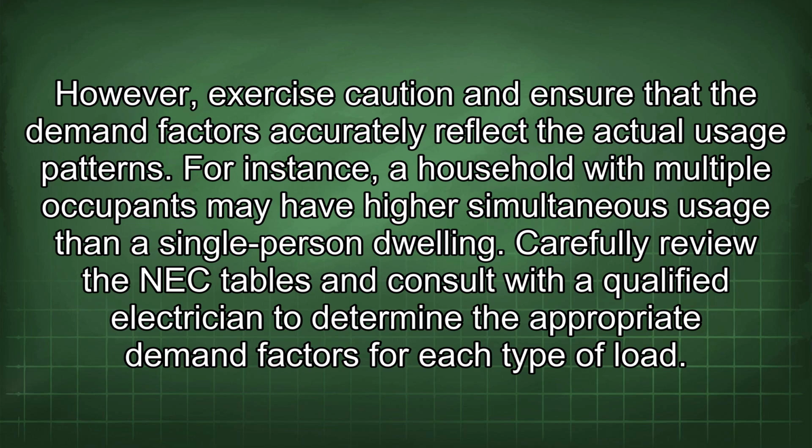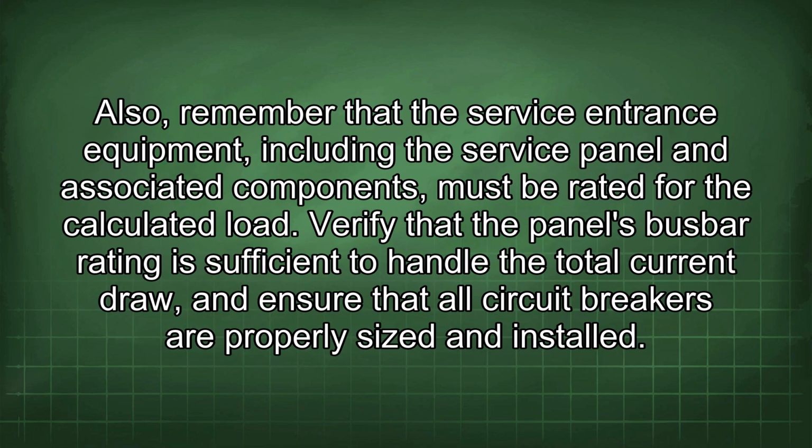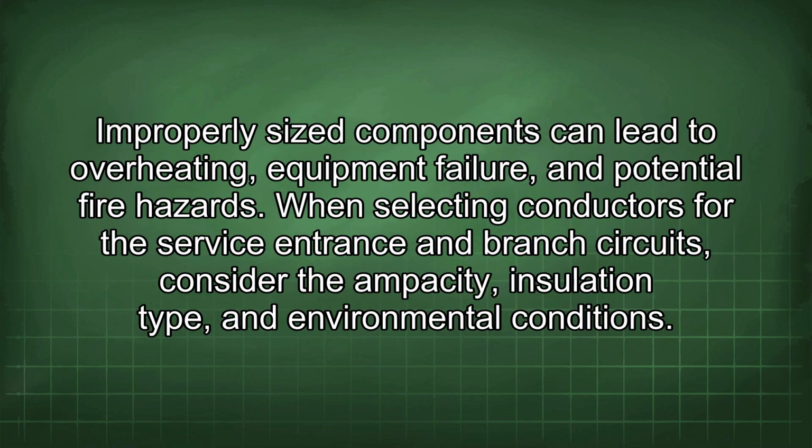Carefully review the NEC tables and consult with a qualified electrician to determine the appropriate demand factors for each type of load. Also, remember that the service entrance equipment, including the service panel and associated components, must be rated for the calculated load. Verify that the panel's busbar rating is sufficient to handle the total current draw, and ensure that all circuit breakers are properly sized and installed. Improperly sized components can lead to overheating, equipment failure, and potential fire hazards.